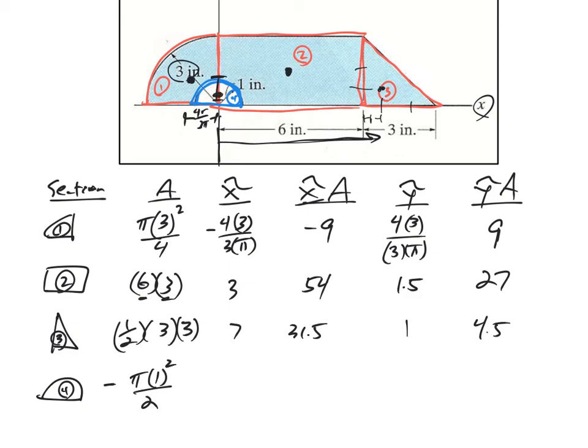Look at that handout, which will be stapled to the last page of your test, and you'll see that for the area of a half circle, it is 4r over 3 pi from there. But in the x direction, it is symmetric, so the x tilde is 0. Where's the centroid along the x-axis? It is at 0. Multiplying those together, 0. Here the y is 4r over 3 pi. Multiplying those together, negative 0.667.